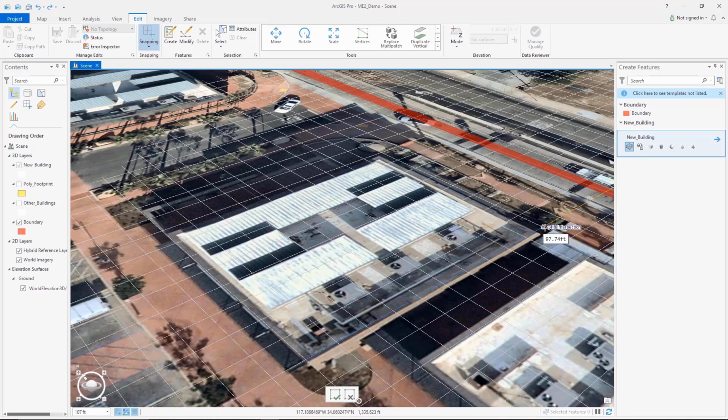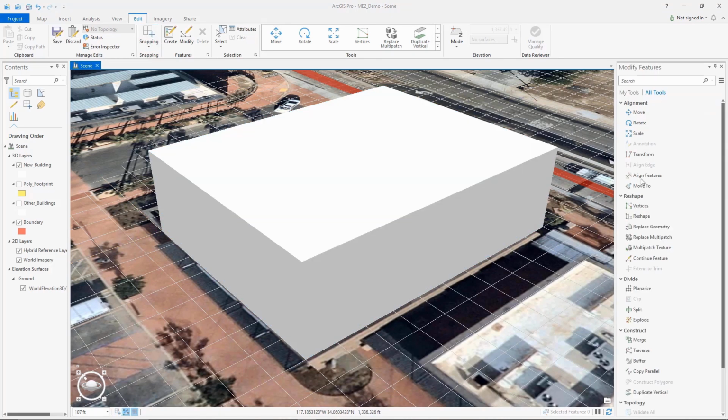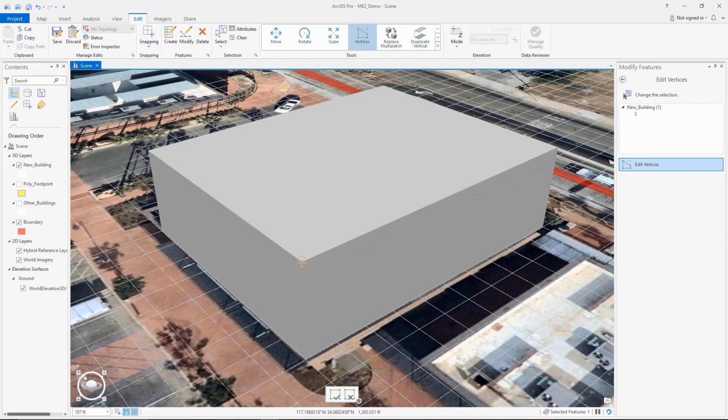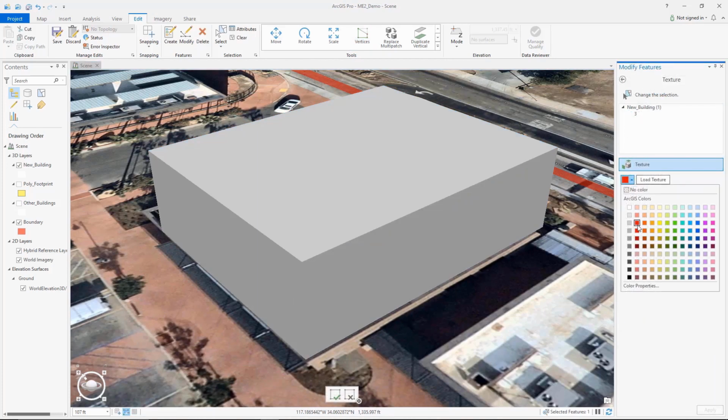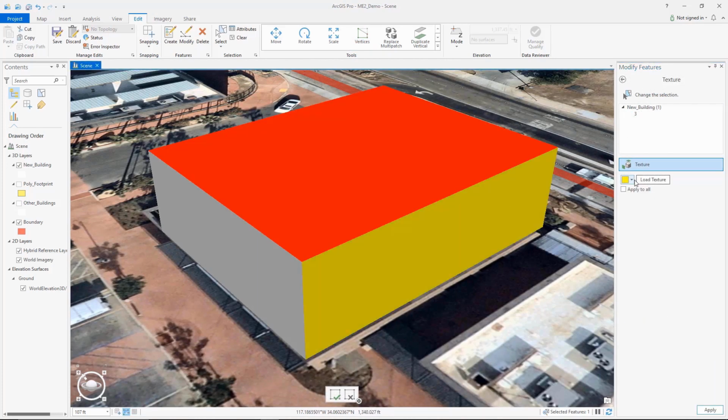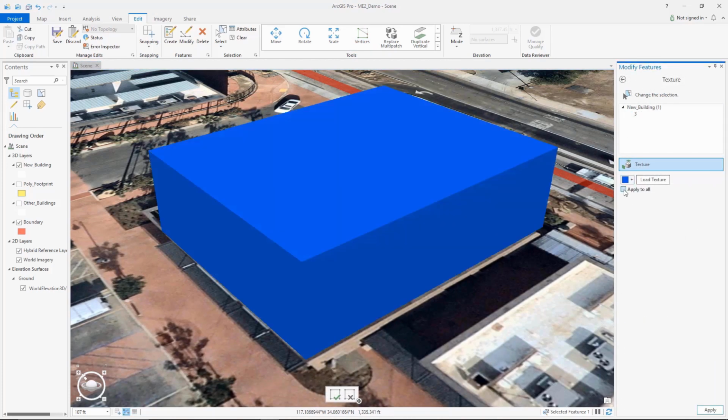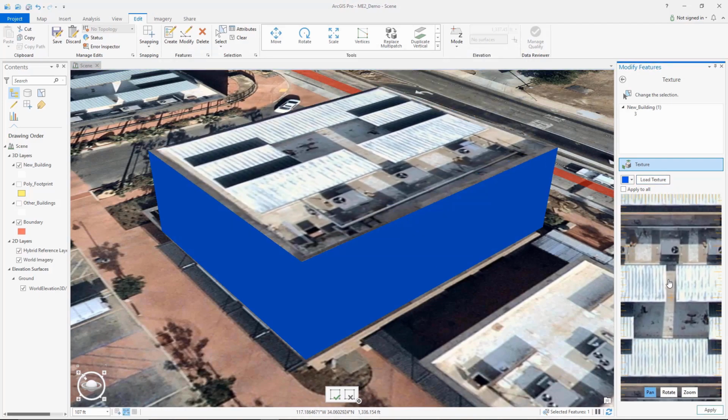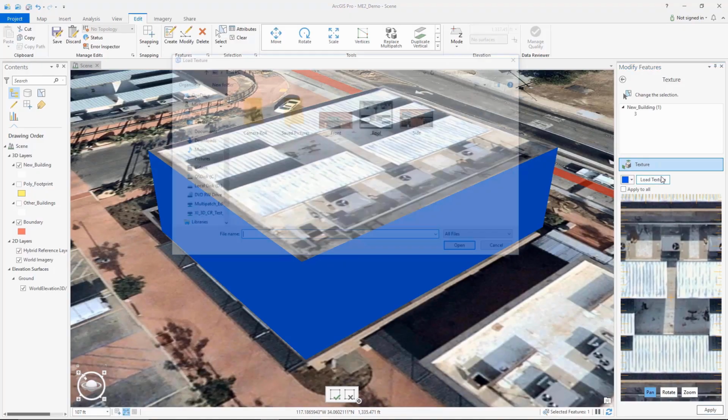You now have the ability to edit 3D multi-patches with high accuracy by using the 3D and interactive feedback constraints. You also have the ability to edit individual vertex nodes of a multi-patch by either interacting with them via absolute or delta move. You can also apply solid colors to individual faces along with custom textures and the ability to move, rotate, and scale.